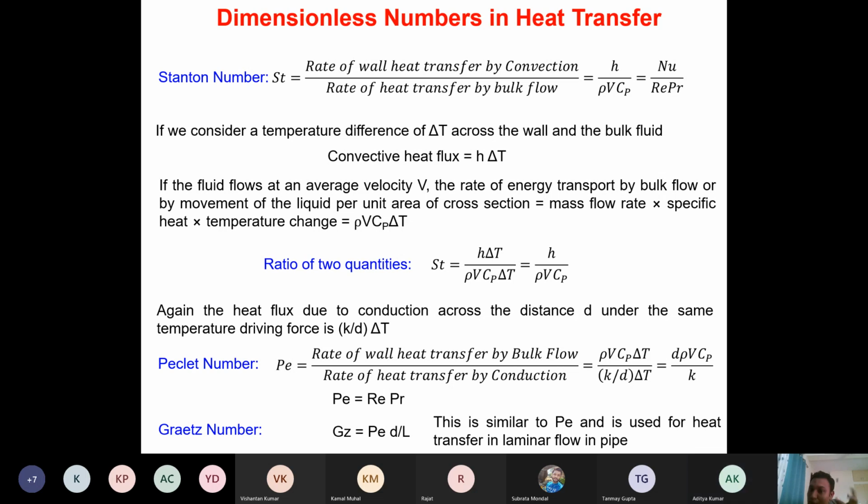But why are these used? The rationale is that in some physical cases, remember the Buckingham Pi theorem is silent about the structure, but when you are making correlations, in some cases the Nusselt number divided by Reynolds number and Prandtl number, this entire factor, becomes important. This comes out directly from the experiments, isn't it? So there, in general, the Stanton number is used.